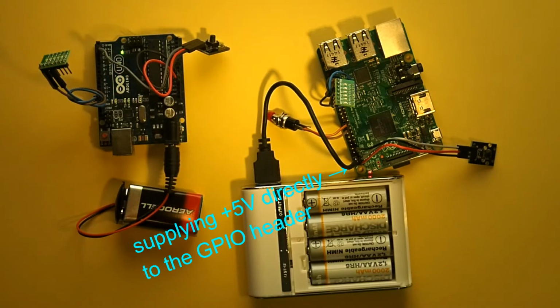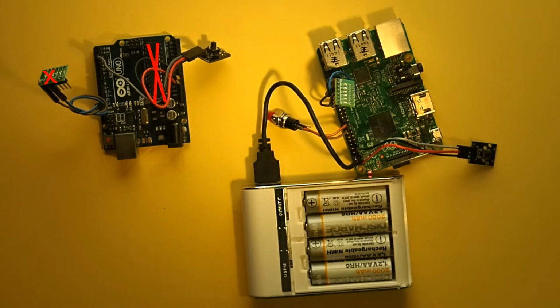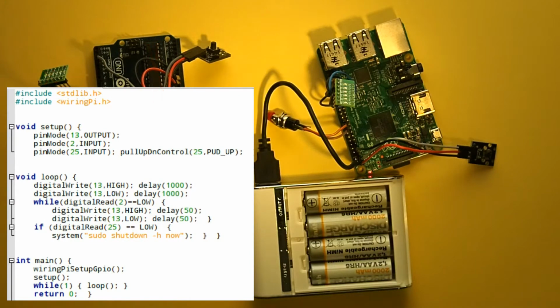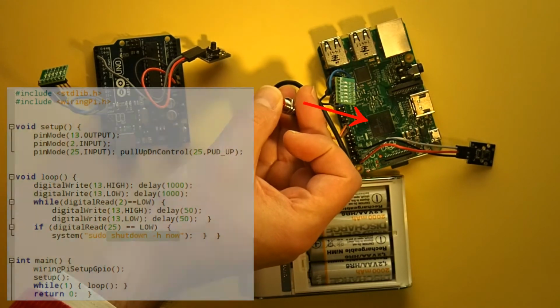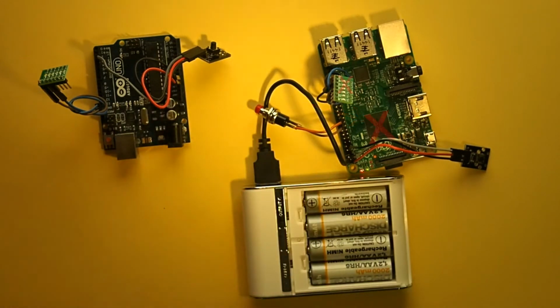We who use computers understand that computers need to be shut down nicely. You know that one shouldn't just disconnect the power supply of a computer as we are used to doing with Arduinos. For instance, in this program, connecting a certain GPIO line down to the ground indicates to this computer that it should now start shutting itself down.